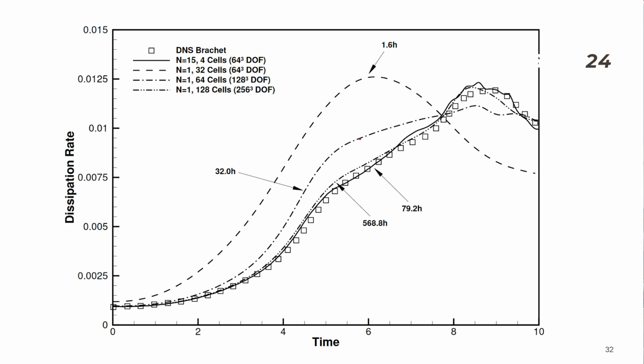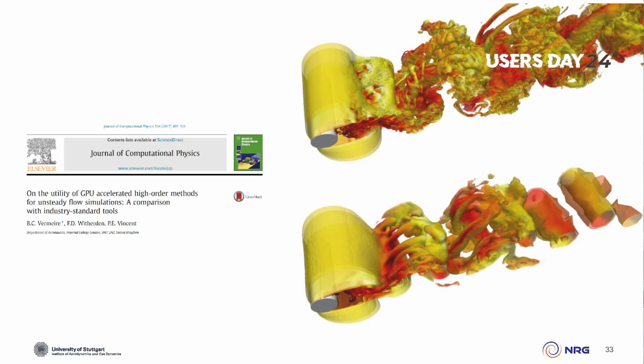So the dashed line and the solid line correspond to these two images here, right? And you can see this only takes 2 hours. That's true, it's much faster to compute, but it's also much farther away from the actual physical truth that we are trying to approximate. I can now, of course, do an H convergence series, so make the grid finer and finer, and then I end up with this line here. But as you can see, to achieve approximately in the L2 norm the same accuracy, I'm at 500 and something hours.